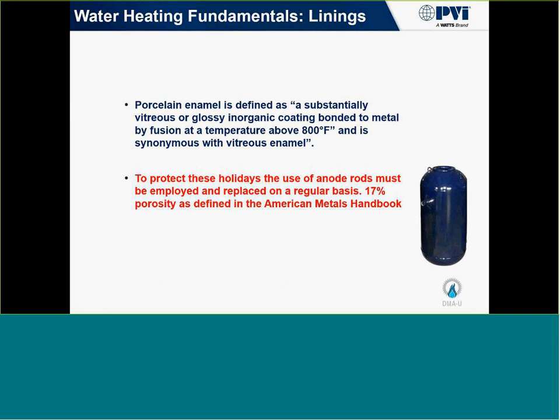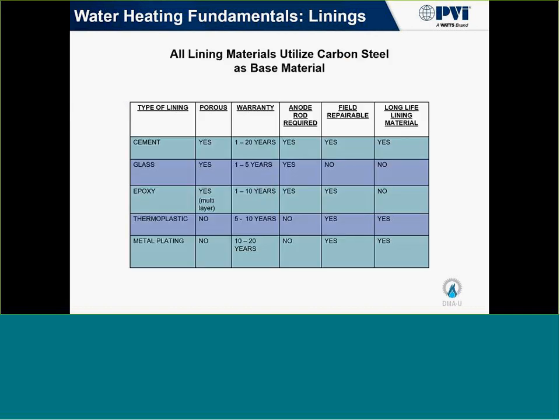Traditionally, people will say a glass-lined tank. What that actually is, is a porcelain enamel. They basically make the inner lining a glass, okay? That is probably 90% of the carbon steel tanks out there. That's the process they use in order to protect the carbon steel inside of it: they basically coat it with a porcelain enamel or glass.